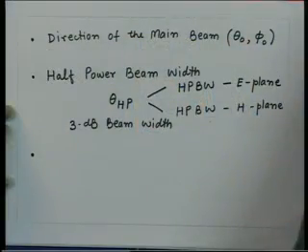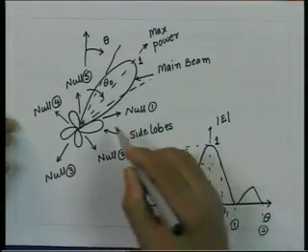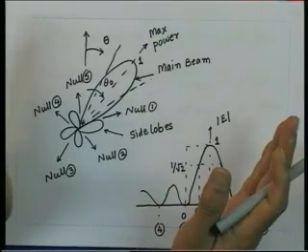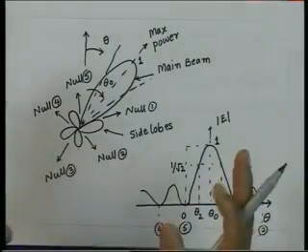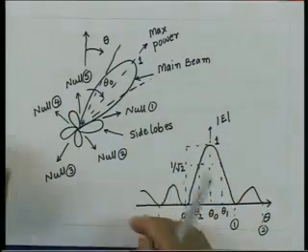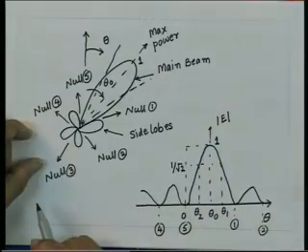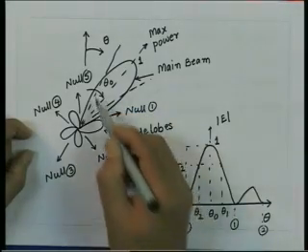Then we have the third characteristic of the radiation pattern. If I ask what is the effective angle over which the radiation goes, though I may accept a variation, the field should not be 0 within that region. So, I may go as far as these nulls, and then I can define the beam width between the first nulls.